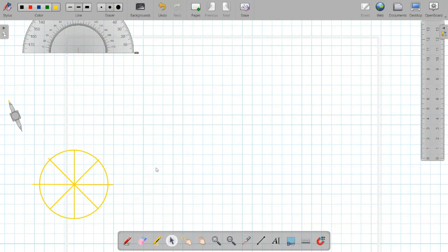Now we have to make a horizontal floor on which it will roll. So the length of the horizontal floor which we'll make will be equal to the circumference of the circle. Again, I repeat, once we have made this circle, we have to roll it on a horizontal plane for one complete revolution. And one complete revolution means the length of the floor will be the circumference of the circle. So you have to calculate